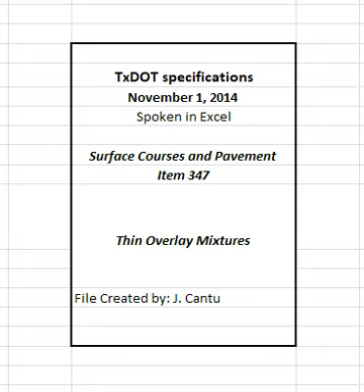The target laboratory molded density, or end design level when using the SGC. Results of all applicable tests. The mixing and molding temperatures. The signature of the Level 2 person or persons that performed the design. The date the mixture design was performed, and a unique identification number for the mixture design.